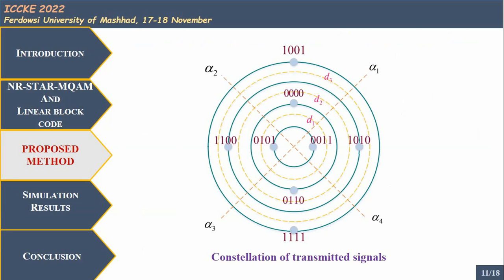The output code words are modulated by 4-ring star 16 QAM modulation. In this case, the code words are selected 4 bits at a time. It means that at first U0, U1, P0, P1 are modulated, and then U2, U3, P2, P3 will be modulated. If we look at the output of the code words, we have only 8 of the 16 possible signal points.